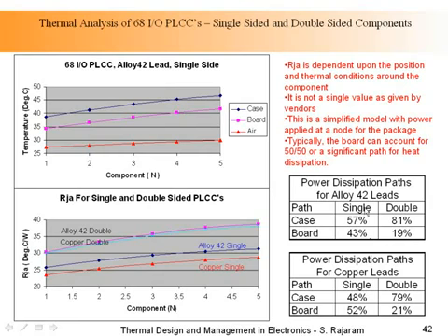So what I wanted to point out to you is that typically in most designs where there are only components on one side, both the board and the package equally dissipate heat from the front and the back side. Now, if you put more on the double-sided, obviously there's less board area and most of the heat will go through the package. So these are all well understood. It's been studied for a long time, and we do analysis to determine what the temperatures are inside the junction, and then we do the measurements to follow up with that.